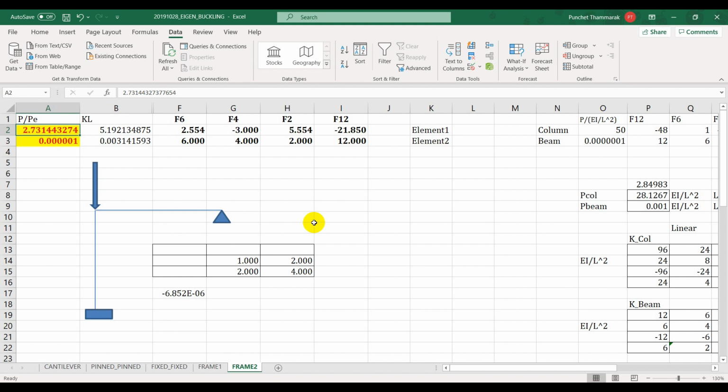And you'll be able to determine the buckling load in a different way. Because right now we do the Eigen buckling. Later we will not do Eigen buckling anymore because it's not just the one sharp bifurcation point. The system may deform and then undergo very, very large deformation. So we will figure out where we will allow our structure to withstand the load, because when deformation is too big, you lose the stability and so on and so forth, right? But you don't have the bifurcation point and it's no longer Eigen buckling. Well, why? Because if you look at the